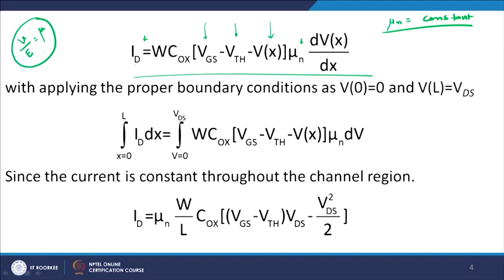So constant primarily means that, and if you plot for silicon, velocity versus electric field, it looks something like this. So this is the region where V by E is constant. Similarly here is the region where V by E is constant. Somewhere here you have a nonlinear mobility profile, so here it is nonlinear. But let us assume we are not going to that high electric fields, you are restricting yourself to low electric fields and velocities are small, and therefore I can safely assume that V by E is constant, which is equals to the mobility.